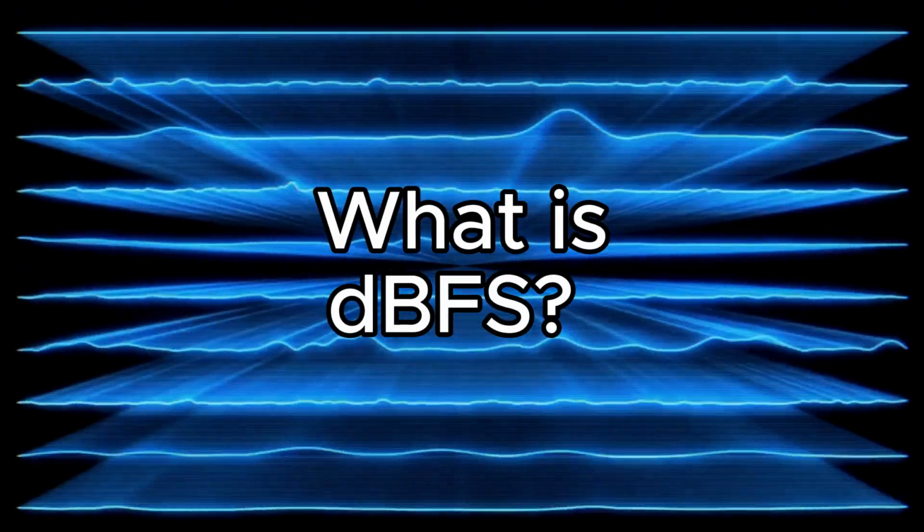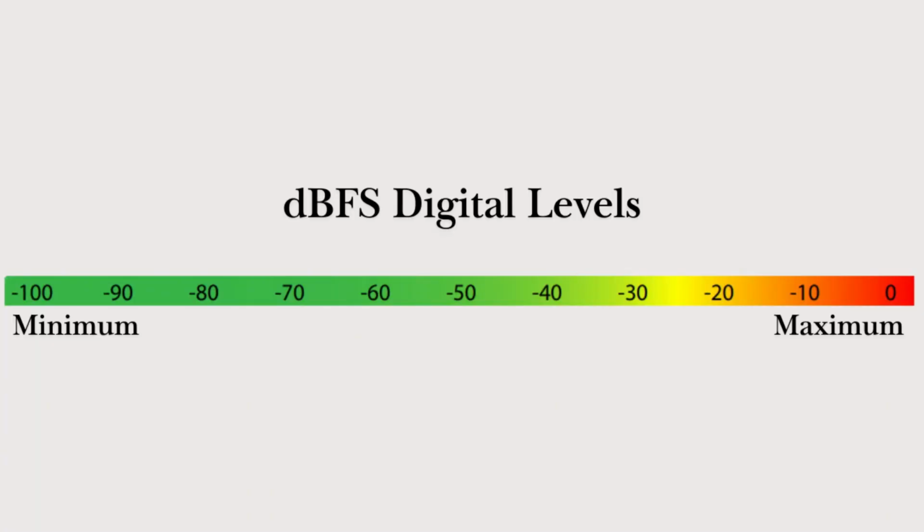I'm not putting the equation up for dBFS just yet because the equation for dBFS utilizes bit depth information, which is going to be a lesson dedicated to itself. So what is dBFS? dBFS is a digital scale which indicates the minimum and maximum level that a computer or a digital console can reproduce, with its lowest measurement being negative 100 or infinity, all the way up to 0 dB. Again, the important thing to understand about the dB is it's a ratio between two powers, whether it's in air pressure, electricity, or in the computer domain.